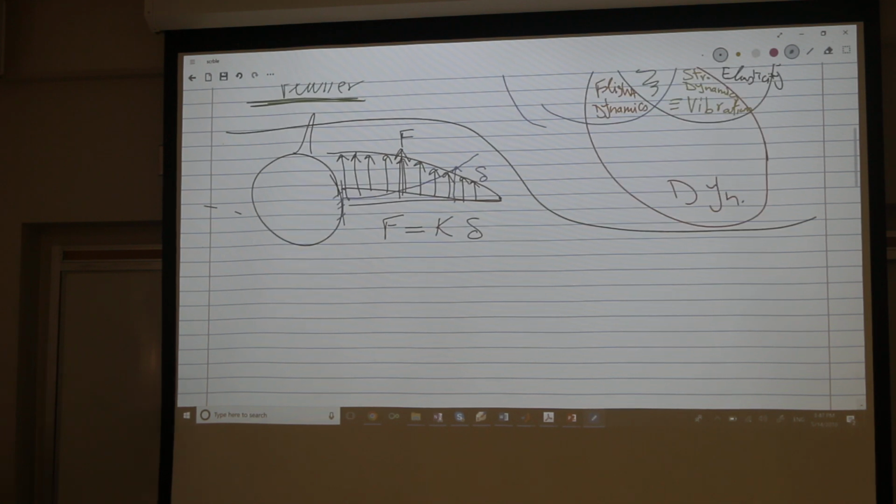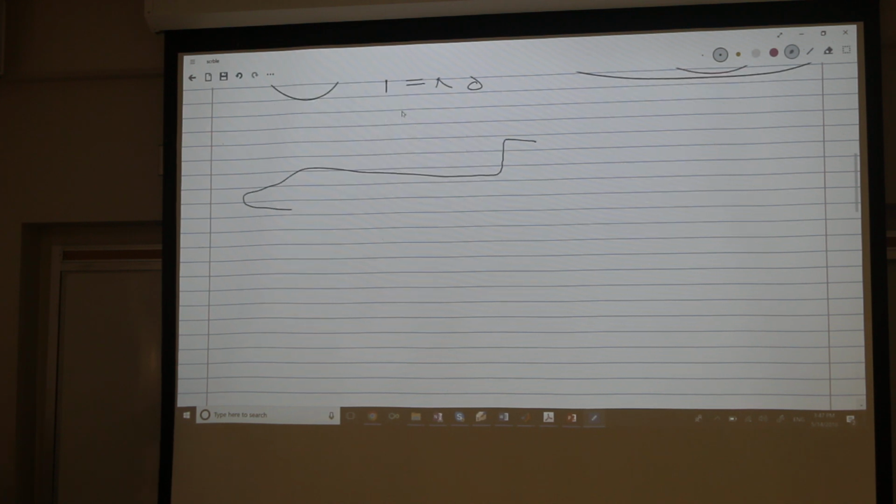Another view of it. Have your wing like this. So the aerodynamics produce forces, lift force, distribution of lift forces, right? Becomes smaller and smaller. But also what? When you have an airfoil, you have lift, what else? Drag. Drag, and what else? Lift, drag, and the triplet is what? Lift, drag, and what? Pitching moment, exactly. So you have a pitching moment.